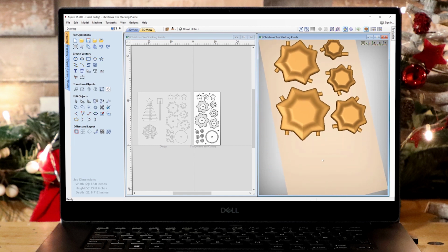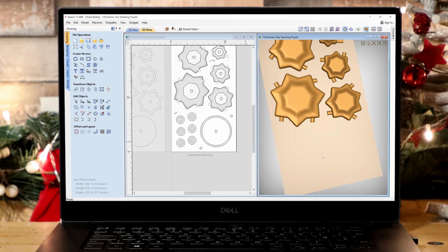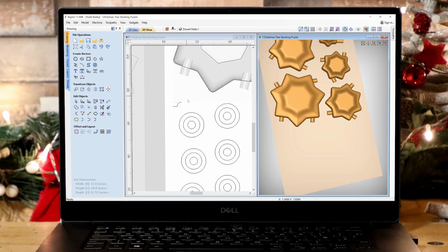And at the bottom here, we're going to have a base and the actual trunk. Now, I've opted to use a special toolpath strategy to create the base and the trunk, and that's called a molding toolpath, where I actually take a specific tool, this would be a ball nose tool, so a tool with a rounded end, and run it around a vector, but using this profile to define that shape.